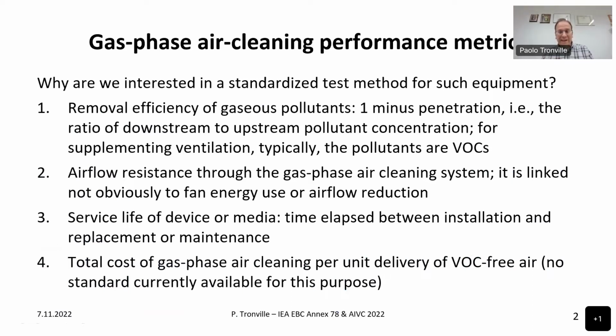This is very critical for gas phase devices because in many cases the pressure drop does not change during the service life, so pressure drop cannot be used as an indicator for the need to replace the device. And fourth, it would be interesting also to know the total cost of gas phase cleaning per unit delivery of VOC-free air. But unfortunately, as of now, we don't have any standard to make this evaluation.